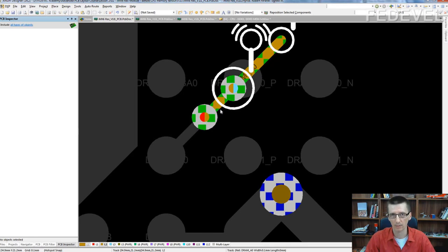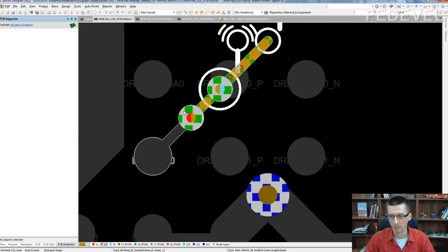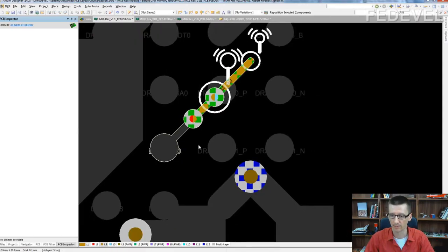Because you can make micro vias from layer 1 directly to layer 3. You remember the ratio between hole and the length? If we use micro vias from layer 1 to layer 3, these micro vias would need to be bigger, and it would not really help us with layout in high density areas. That's why we use layer 1 to layer 2 and then layer 2 to layer 3 micro vias.